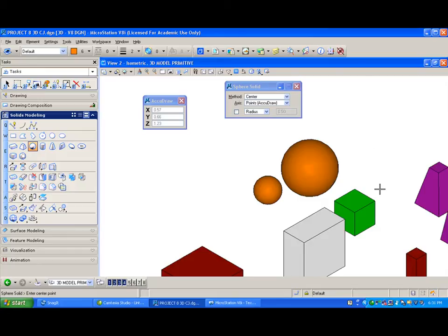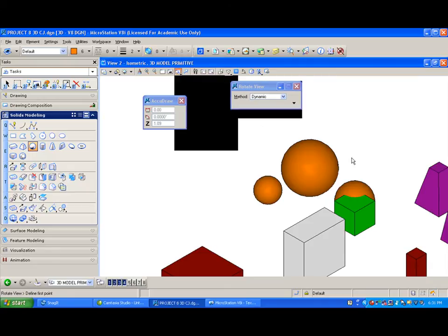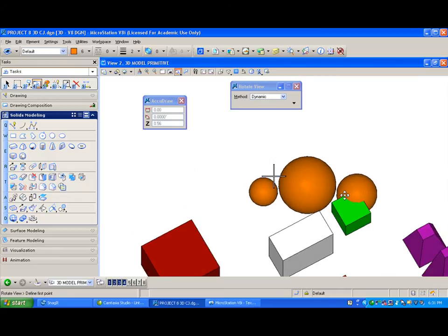And let's imagine we want to put this sphere right on the center of this box. If I hit spacebar C for center, you'll notice it puts me right at the center point. I can come right out to this edge, and left click. That doesn't look right. Rotate it. You can see that that's why we're off on it.